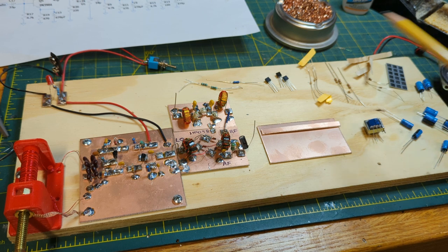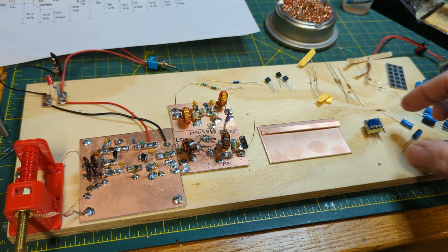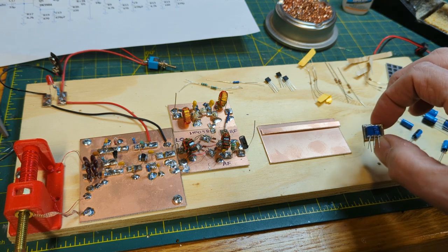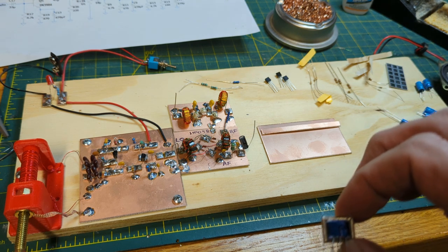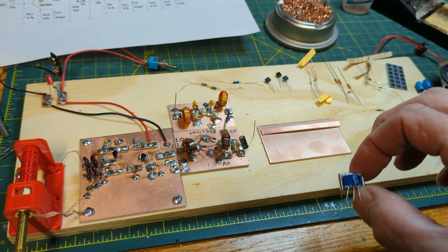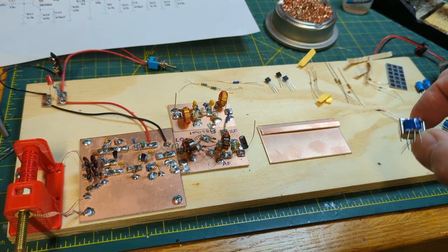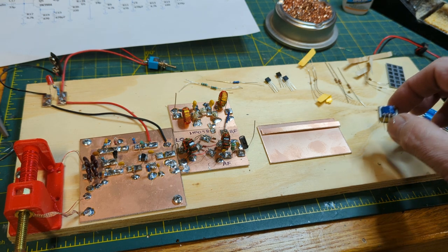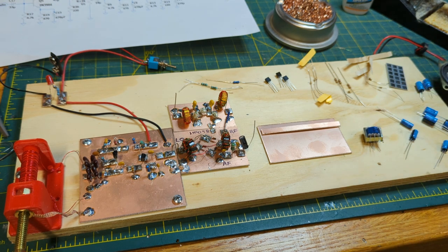And of the components, the one that is possibly going to give you trouble is the transformer, because it has to go in the right way. Now, if you happen to buy the transformers from Mouser that were suggested, they have a black P on one side of them. That's the primary side. That's the side that goes towards the transistor, and then the other side goes towards the speaker.